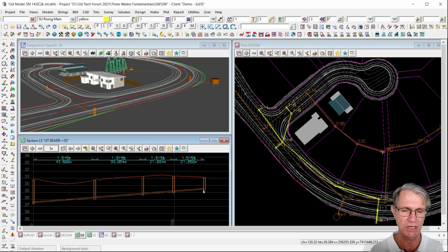This is so that we can connect our houses, our properties into this line, and the line will be deep enough. The deal with sewer is that it's one of the very first things that are built on the project. It may be built after the lots are regraded, and it may even go in before the regrading. So what we need to do is make sure that it's deep enough. And we have some tools that allow us to calculate the required depth just to make sure that the thing is deep enough. There are 2 things that work in tandem.